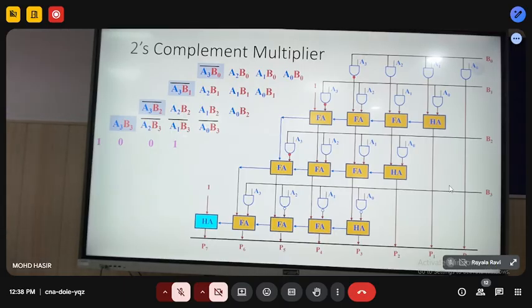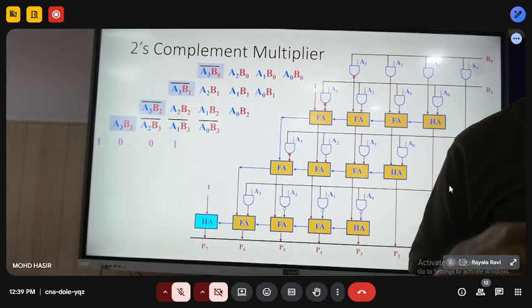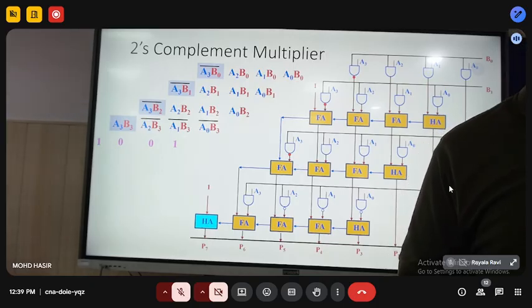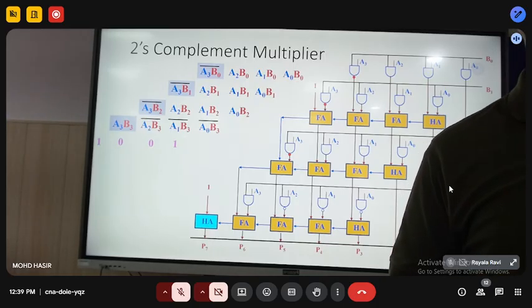And then this becomes a 2's complement multiplier, which is proposed by Baugh and Wooley, so known as Baugh-Wooley multiplier, which has got similar structure like the previous one. No redundant architecture is required. Hardware is required, but it can work for positive as well as negative. So this Baugh paper is available, published in 1973. So then there are different multipliers, Wallace multiplier, tree multiplier, etc., etc.